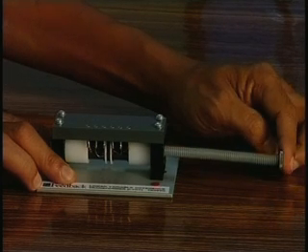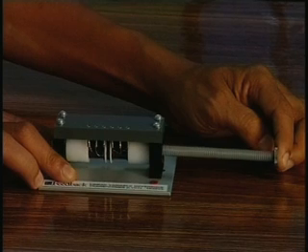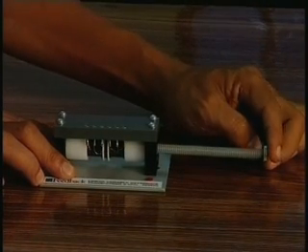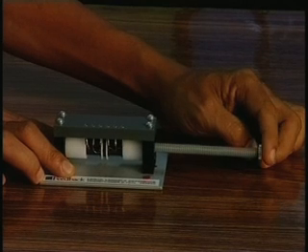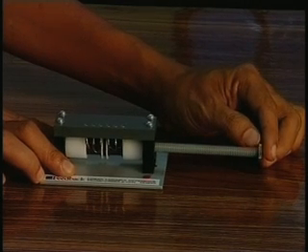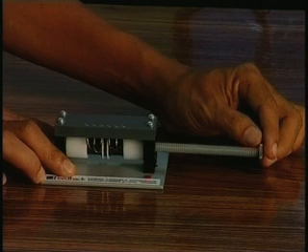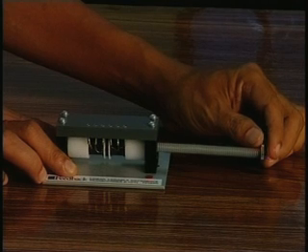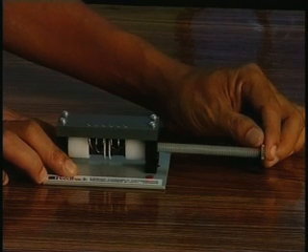And since there are two secondaries, what will happen if you put them in opposition? Obviously, you will get some output voltage, and when it is exactly at the null position, the output voltages of the two secondary coils will be nullified, and I will get 0 voltage. But any position other than that will give you a non-zero output voltage. So, LVDT we have already discussed in detail. So, this is actually a pictorial view of the LVDT.